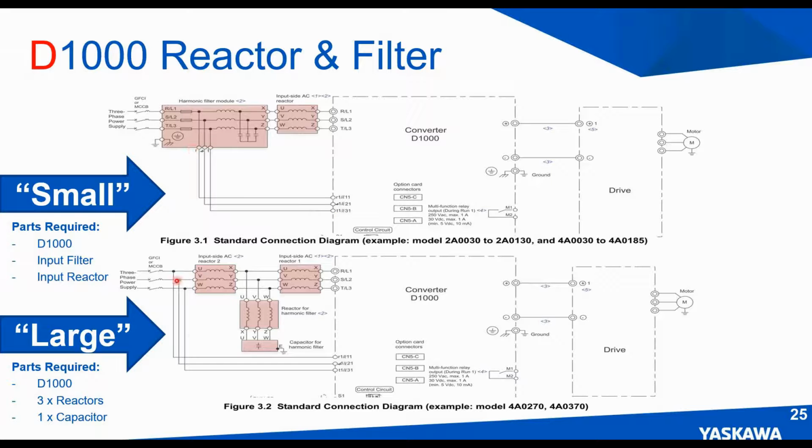These phase detection circuits are key to the operation of the D1000. The misconnection of these detection circuits is the leading cause for D1000 installation and startup faults. The R1000 also has these phase detection circuits, so they're crucial in making sure that OV and OC is overcome. Essentially, if you make sure that your installation is clean and done properly, these things power up and run immediately.